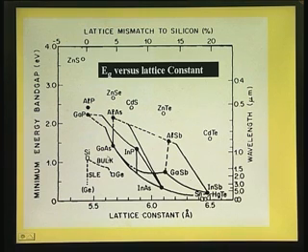The entire thing is a solid line here, because indium arsenide is direct band gap, gallium arsenide is direct band gap. So, any combination is direct band gap. Now, we can have here indium phosphide, which actually has a slightly higher band gap compared to that here, and that is also direct band gap. I can mix gallium indium arsenide of this composition with indium phosphide, or I can grow gallium indium arsenide on indium phosphide.